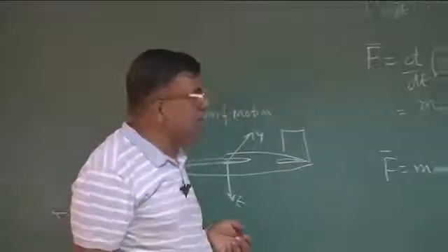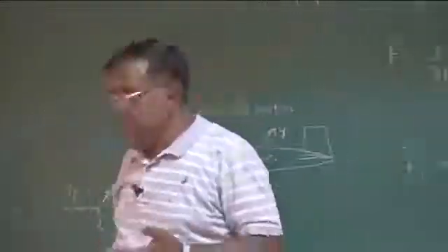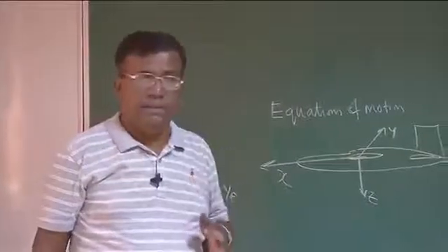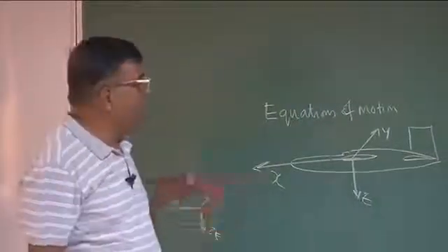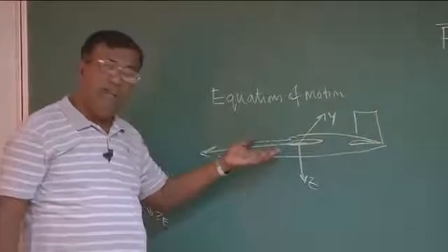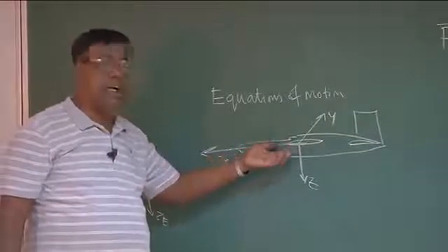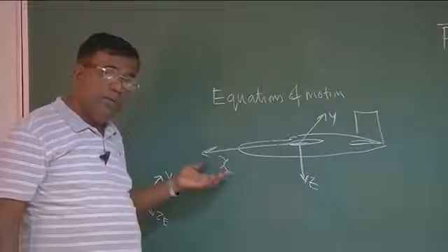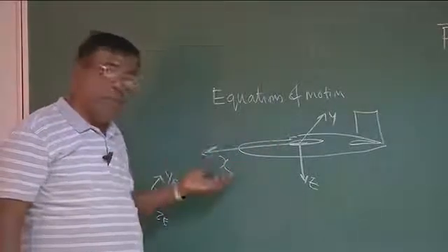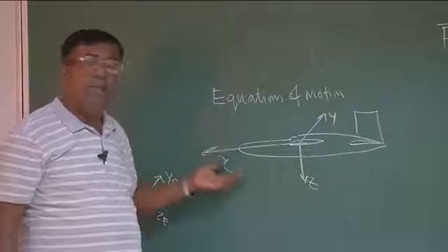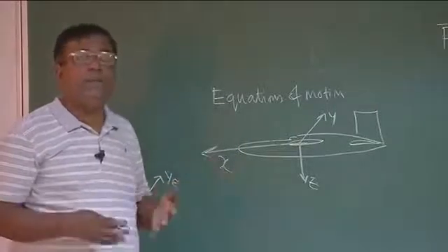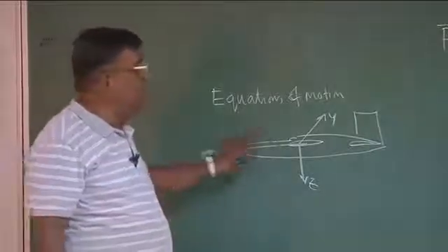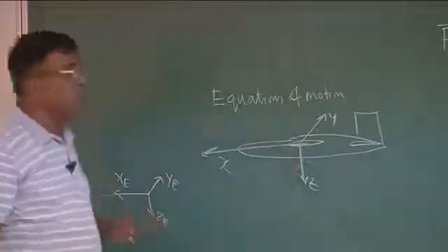The second thing we realize is that the aerodynamic forces depend upon the relative airspeed. So from that angle, the body fixed frame will be very, very important. The speed of the aircraft with respect to the atmosphere, relative to wind, will be very, very useful, because aerodynamic forces depend upon relative air velocity. So we had a motivation to work in the body frame for these two reasons.